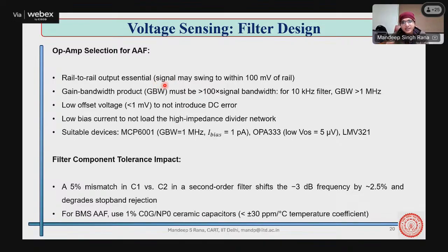It does not have a necessity to be given at least 1 volt at the input before it starts working, or at most 4 volt beyond which I cannot work. This type of situation is generally present in all op amps which are not rail to rail. So rail-to-rail op amp is a terminology which we want to have in our op amp.